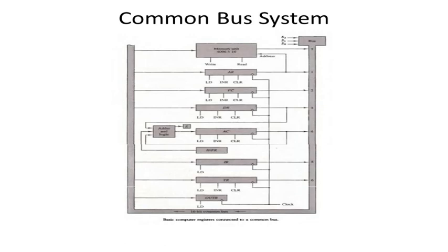Each register is also connected with 3 inputs: load, increment, and clear. Load means the data coming through this bus line is entered into this AR through the load input. Increment means the register content will be incremented, so here the address in AR will be incremented by 1. Clear means if you want to clear the register, you can clear it.